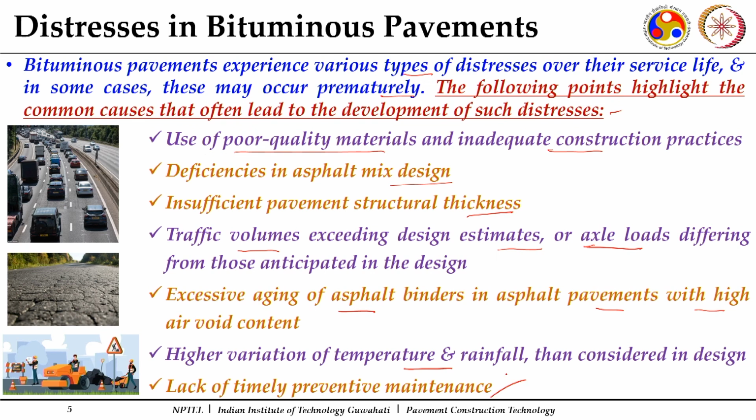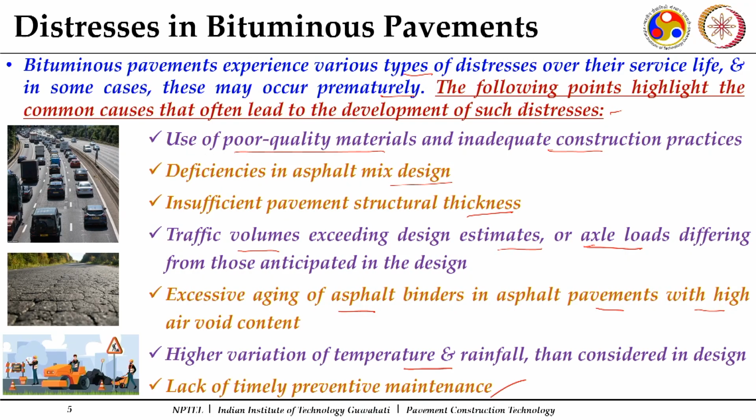Lack of preventive maintenance jobs: some regular routine maintenance has to be carried out and some preventive maintenance activities have to be carried out. In the next lecture, we will discuss those maintenance activities specifically, and the general treatments. So, cleaning of your drains has to be there, maintenance of your shoulders has to be there. These exercises need to be done regularly to ensure uniform performance throughout the design life of that particular structure. So, these are some of the common causes because of which one or the other distress takes place in the flexible pavements.